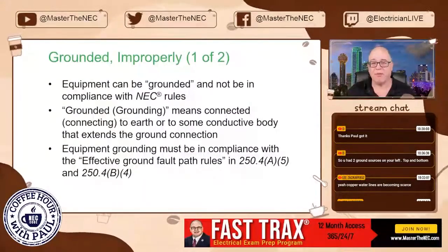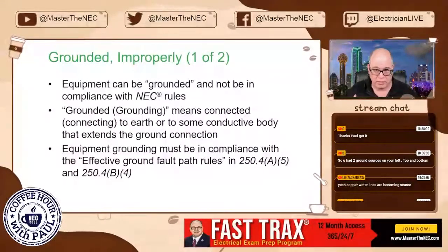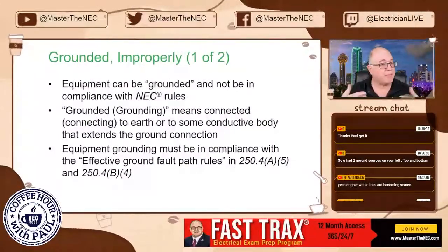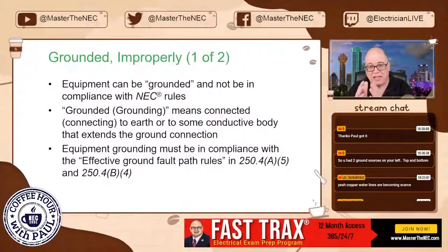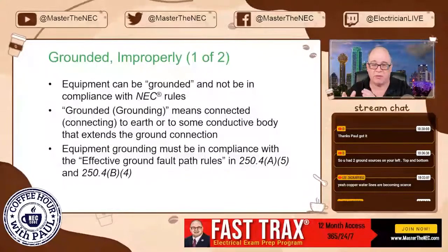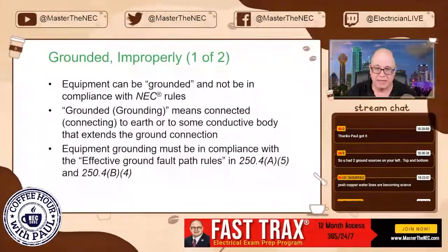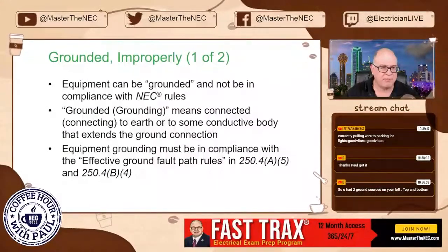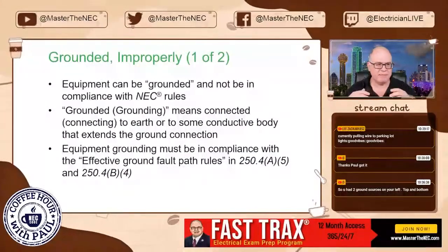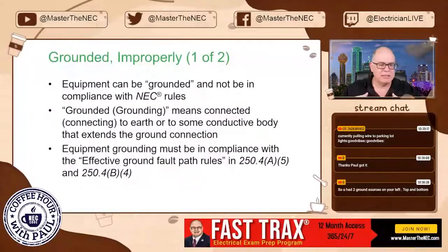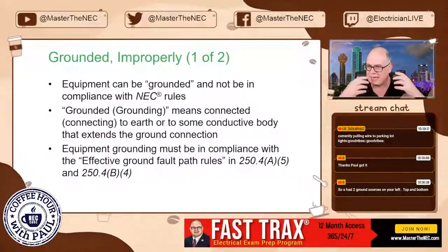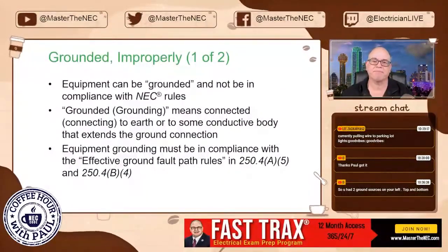The metal framing of a building that is connected to the electrodes or might be the electrode, and we're not talking about the thin sheet metal used for studs, okay? We're talking about the structural framing of a building, okay? Big I-beams, whether they're in the earth 10 feet, those type of things, right? Or all those type of things. So again, that's what we're talking about as an extension, okay?